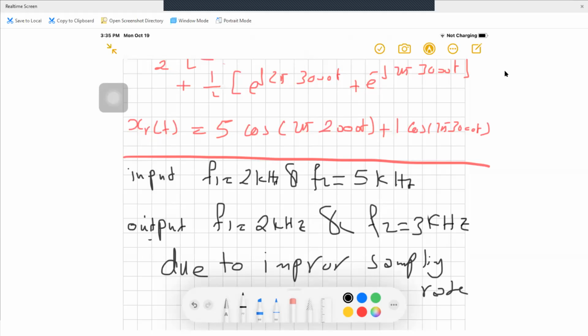Well, it's good. So at least we have to select the sampling rate equal to 10 kilohertz. Of course, 10 kilohertz is not preferable. Why? It requires a very accurate, very sharp edge low pass filter. But if you consider, for example, a sampling rate of 12, 13, 14, 15, or 20 kilohertz, all of these are better than 10 kilohertz.